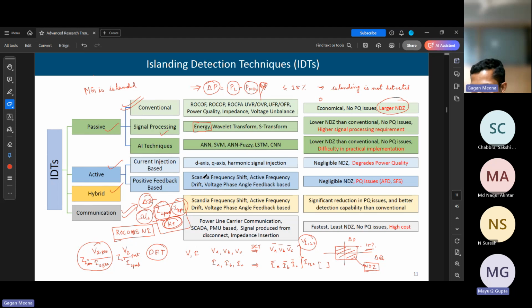The second thing is, do we have a practical relay available in the commercial market which uses this kind of protection scheme? I haven't come across this. Relays with over voltage, under voltage, directional over current, df/dt and all those things are available in combinations, but this protection scheme in the relay, I haven't come across. That's why I'm asking you.